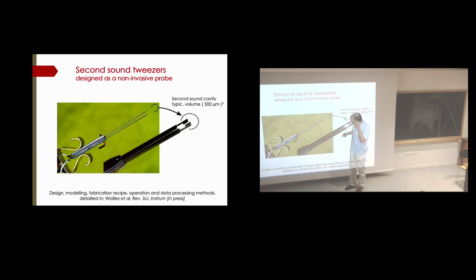So this effect, and the boundary layer condition sets the thickness of the plates. The thickness of the plates here is about 15 micron. To make sure, we can estimate what is the boundary layer which develops. And we know that the second sound wave that we measure mostly measures what is happening in the central region, not on the plates. So this is how it's sized.